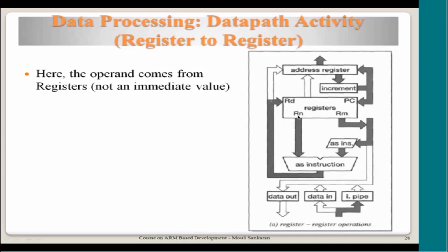Now, this is one of the registers which is moved, actually moved to another RD. When you say MOV RD, RN, a simple example where this RN comes directly and there is no shift operation on that, so this particular thing will not be happening. So this RN will directly fall through the ALU and go into RD. This value is actually read from RN.